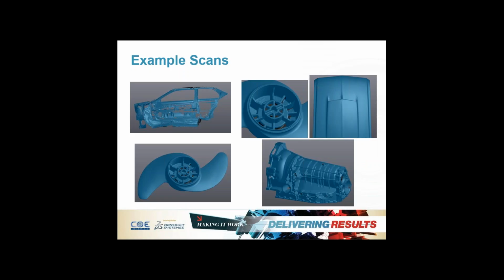Here are some examples of data collected by a 3D scanner. You can see the quality of the 3D scan information is really quite good. Metrology grade scanners typically hold a tolerance of better than 3 thou.